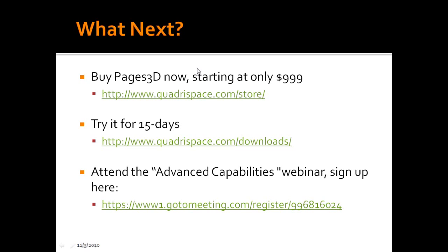Let's see. In regards to the import of updates, how can we retain revision control? The revision control on our side is mostly that we identify the previous CAD files that were imported into the document, and you're able to import a new revision or an old revision.